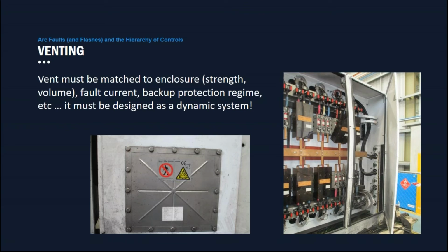And so in this case, it shows it was relatively poorly matched between the strength of the enclosure, or in this case the doors, and the vent itself. Whilst we don't propose to lecture at length on designing arc vents, it is not as simple as selecting a particular static pressure, say 10 kPa or 15 kPa, because these things must work very, very quickly.